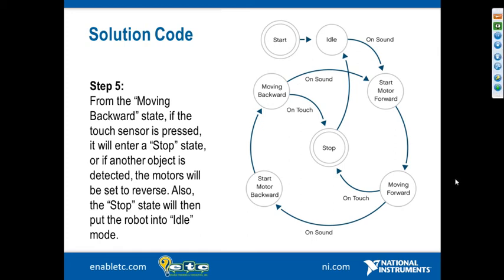So just want to quickly summarize this week's webinar. We investigated a bigger state machine of the state diagram we see here. We learned how to create nested case structures to implement more complicated logic. We saw how the benefits of reusable code allow us to reuse states and to duplicate them really easily. And we learned the importance of proper state machine architecture, including delays and waits and transition statements, so that we could implement arbitrarily complex state machines.